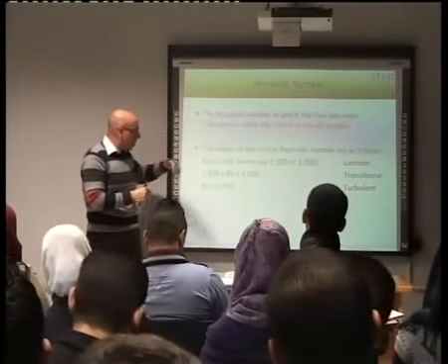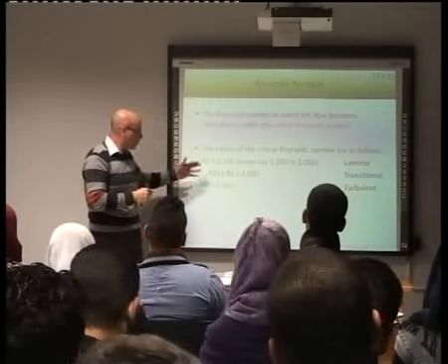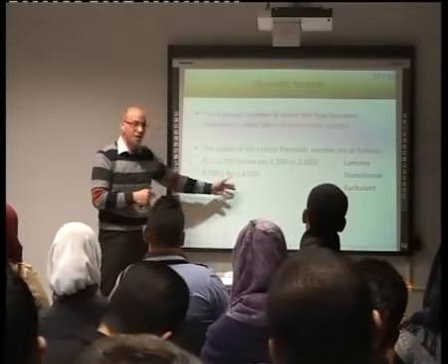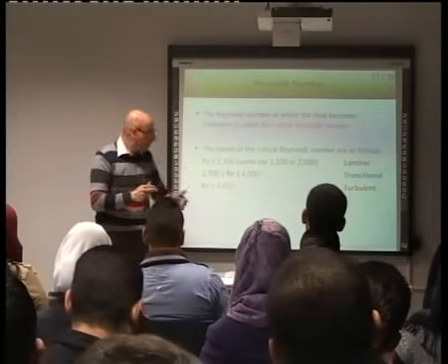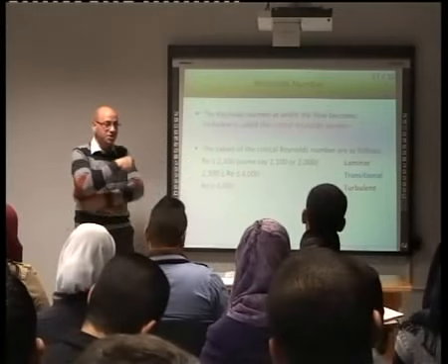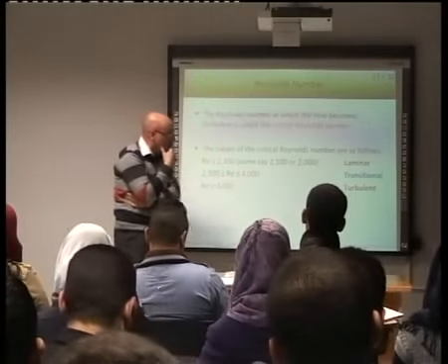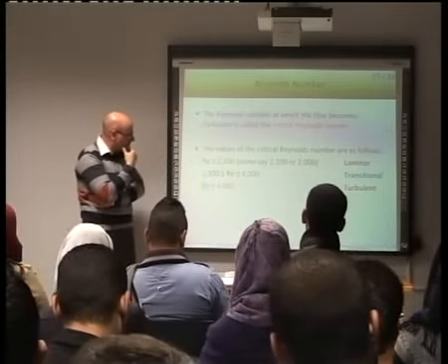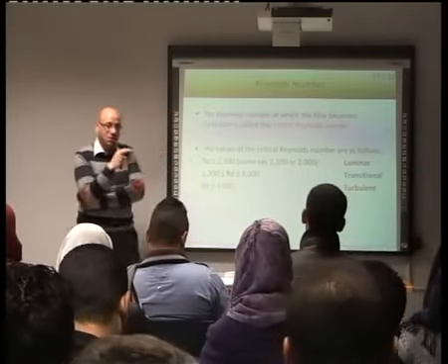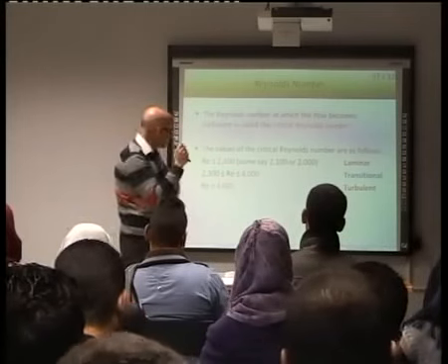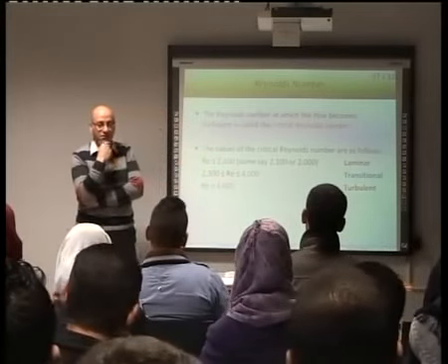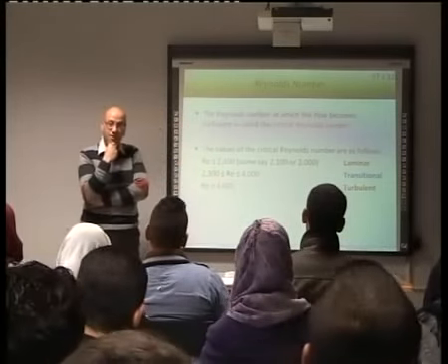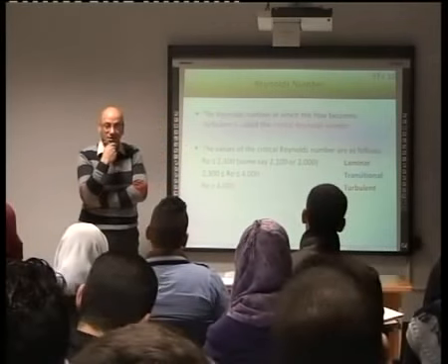If it is really from 2,300 up to 4,000, then this is transitional. And if it is really greater than 4,000, then this is turbulent. Now, two things. The first thing, in reality, this is what I really care about now. Do we have laminar or turbulent flow? Turbulent. Why? Yes, this is right.